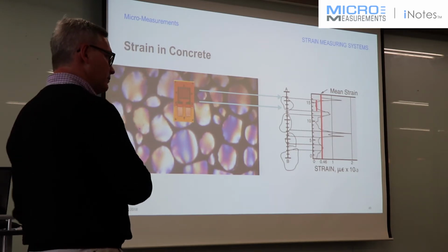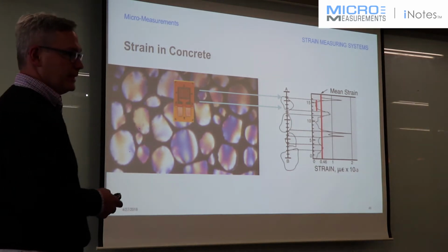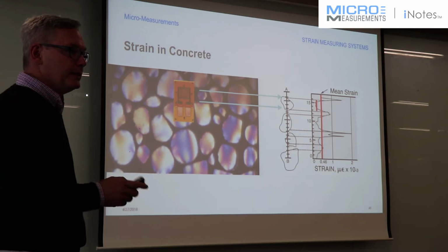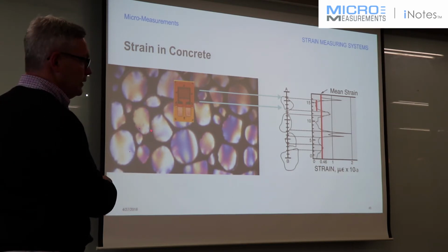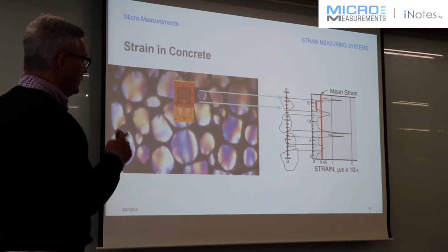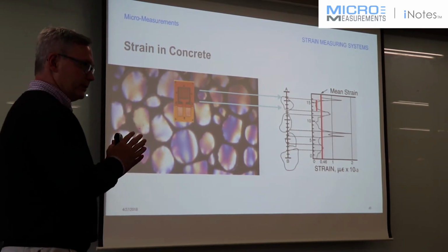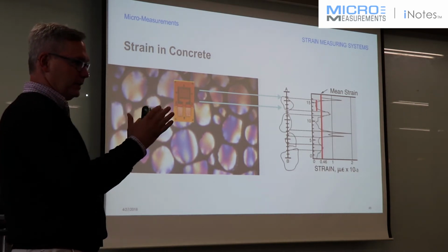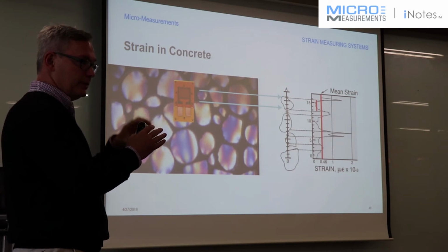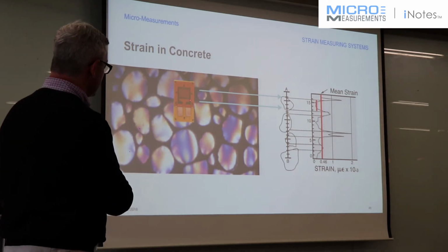And kind of the opposite approach to what VJ was talking about. Here, oftentimes you want to pick a larger size strain gauge. And the reason for that is that when you look at the strain along the surface, it's changing. So, and a lot of times what you're doing is coupon testing or samples. So to get more repeatability from one sample to the next, or from one location to the next on the same sample, a lot of times you pick a little bit larger size gauge.